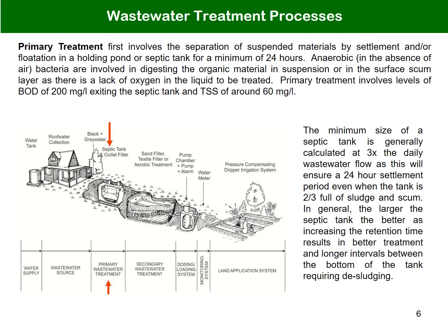Wastewater treatment is broadly divided into 3 categories. Primary treatment is the settlement of solids in a mostly anaerobic environment, usually in a standard septic tank. Secondary treatment is further processing in an aerobic environment. Tertiary treatment is further treatment involving disinfection, often by way of a UV filter or adding chlorine.